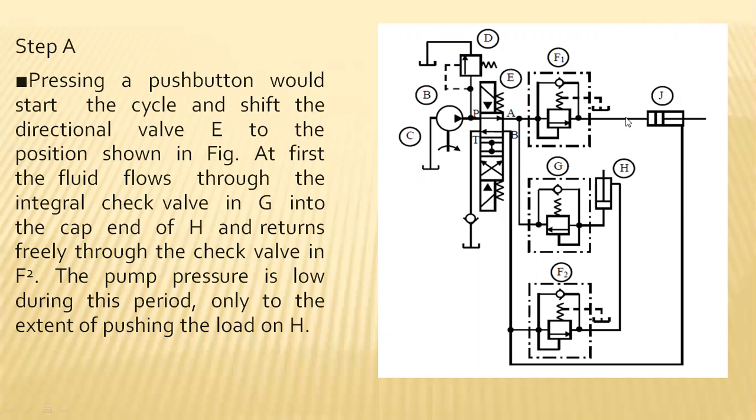So, for example, it is a cylinder and piston arrangement. The fluid with high pressure entering here is being sequenced. So this is the setup, this dotted line internally having this sequence valve, through which the highest pressure will not be let into the actuator indeed to commence the corresponding movement. Either it may be a rotary kind of movement or else a linear kind of movement. In the pictorial representation, we have the linear kind of movement, that is the extension stroke and the contraction stroke.